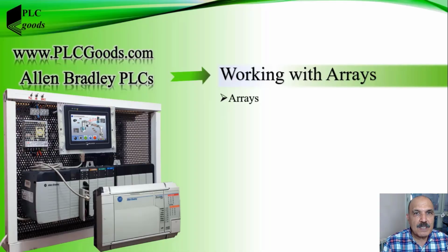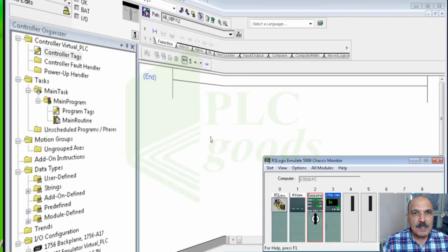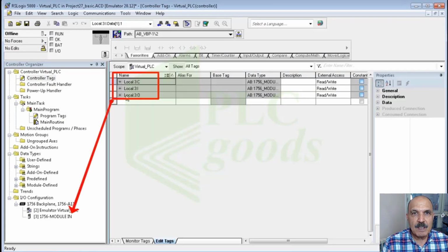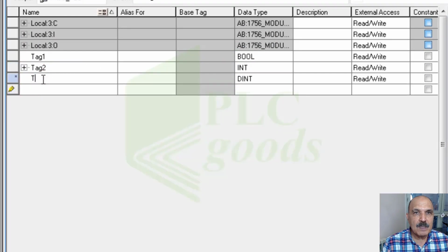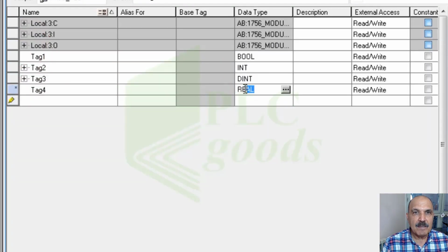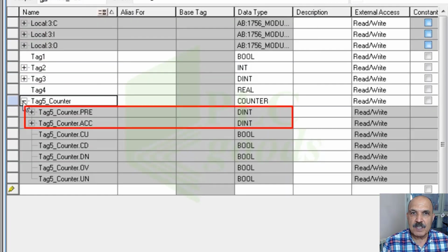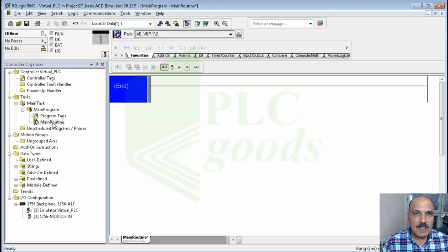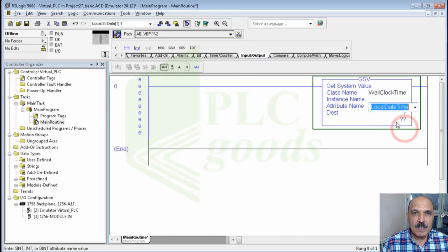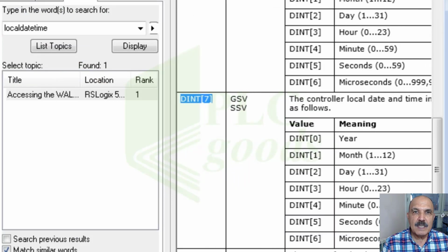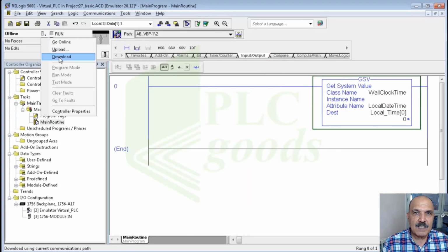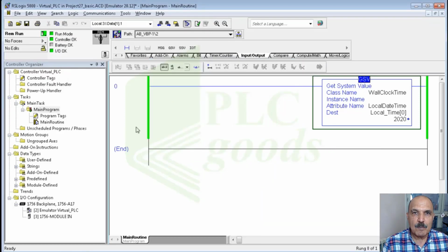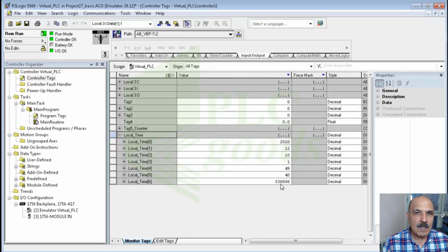Video tutorial lesson number 27 covers various aspects of PLC programming, data types, arrays, and the file MISC group of instructions. It discusses various data types, including Boolean, integer, double integer, and real, as well as other types like timer, message, and alarm.